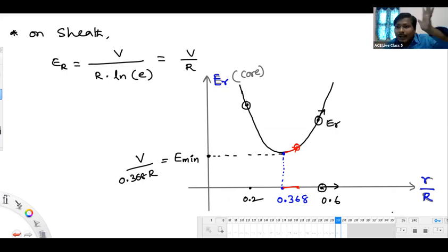Now, if corona occurs, small r is increasing. What will happen to small r by capital R? It will increase, so it will come to more than 0.2. With respect to this increment, what is happening to field intensity now? Increasing or decreasing? Field intensity is decreasing. With respect to the previous field intensity, you got the corona, but the present field intensity is lower than the previous number. Corona may not happen, or may not extend.